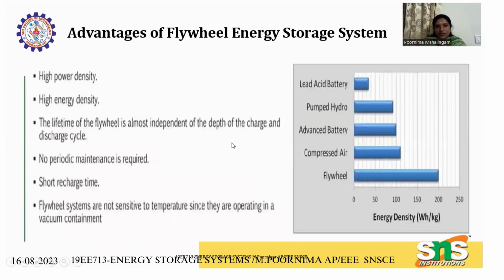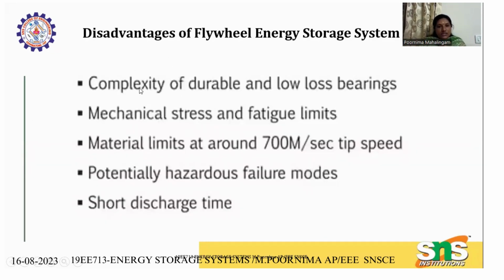These are the advantages. Compared to other storage systems such as compressed air, advanced batteries, pumped hydro or lead acid batteries, the energy density is high in a flywheel. This is the main advantage of the flywheel energy storage system. Then we have the disadvantages: the complexity of durable, low-loss bearings, mechanical stresses, material limits of about 700 meters per second tip speed, potential hazards and failure modes, and short discharging time. These are the main disadvantages.